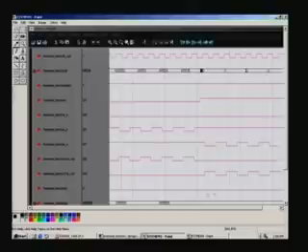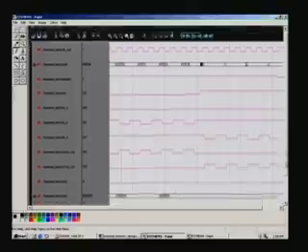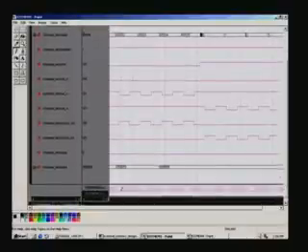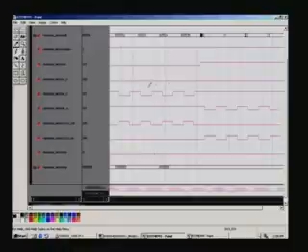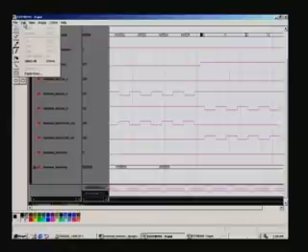And the data now has no change because it is continuously reading the same data, and you can see a huge time has elapsed, and for 65535 locations we have not only written the 555 data, but also cross checked, and you can verify whether there is an error. You can see here, this is the error here, and it is 0. So, there has been no error, and we have seen in the ModelSim window that it reports the test is passed. So, coupled with this it should prove that the whole thing is working, and the zoomed version is here.